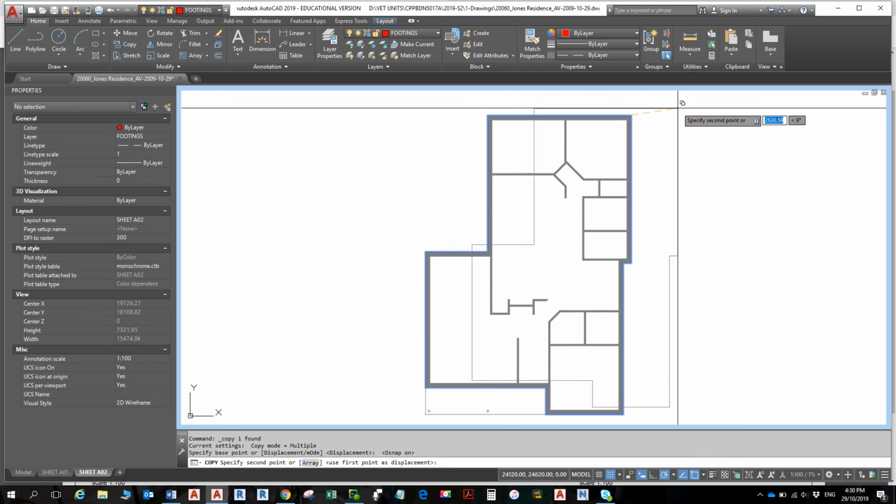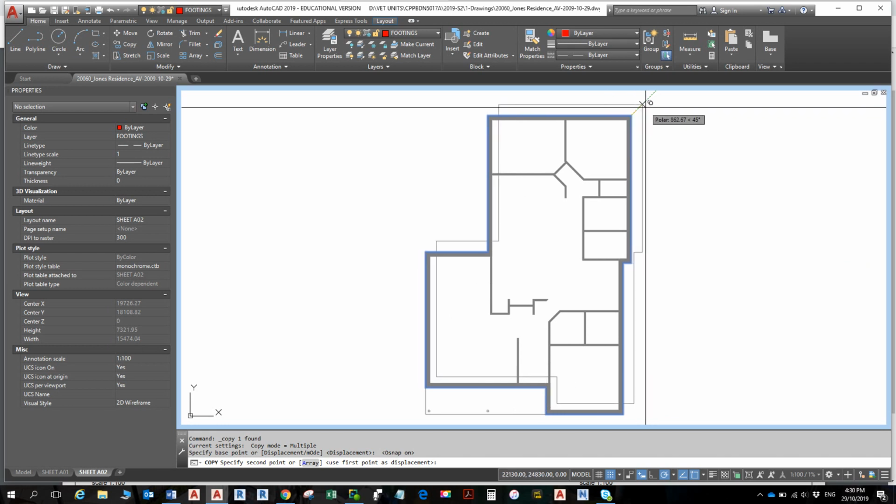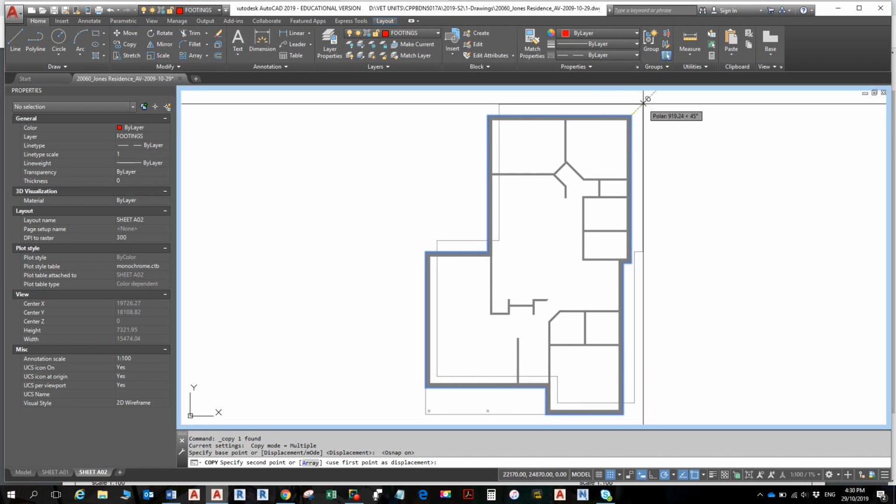Another way of doing that is to copy it from that corner and then, instead of clicking again on top of that and risking perhaps clicking on something that's about a millimeter away, the better way of doing it is to use the shift key and @ for the second position, which means it's exactly from where I copied it before, pasted at the same spot basically. So I did that @, which I don't know where it went. I'm just going to go enter.